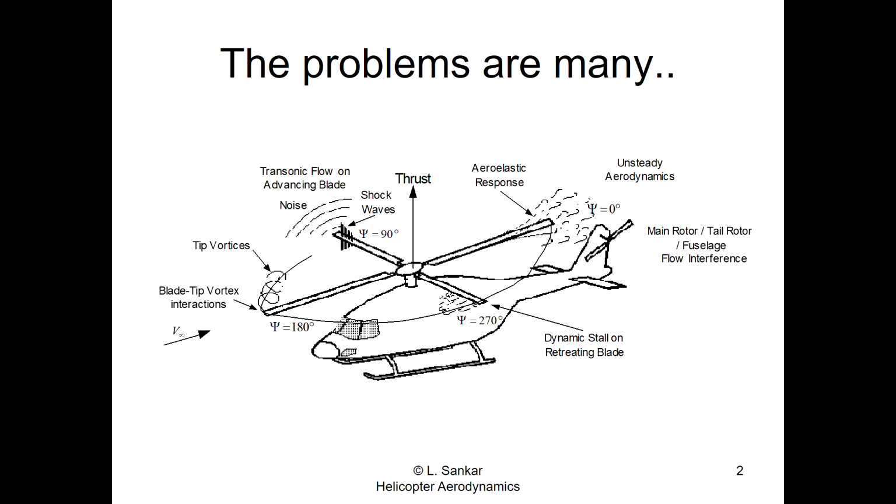So it will be dynamically stalling, in and out of stall, every rotation. So this is called a dynamic stall phenomenon. Dynamic stall causes abrupt rise and fall of lift. It produces its own vortex structure, separated flow over the aerofoil. It produces the nose-down pitching moment on the blades. So all these moments get transmitted to the hub.